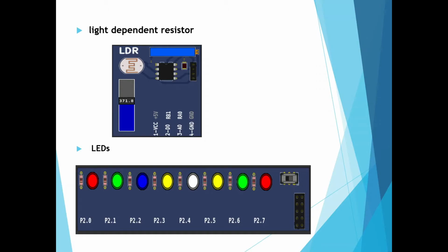Its advantages are that LDRs are cheap and readily available in many sizes and shapes. They need very small power and voltage for their operation. Its disadvantage is that it is highly inaccurate, with a response time of about tens or hundreds of milliseconds.